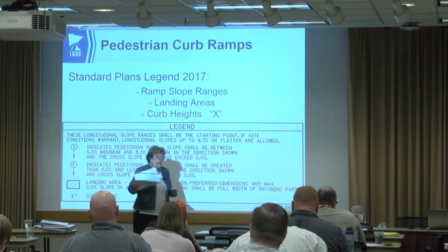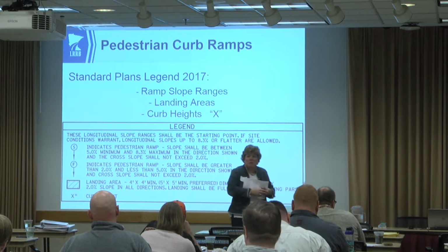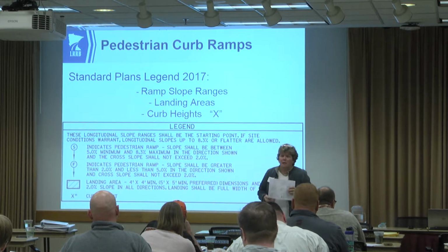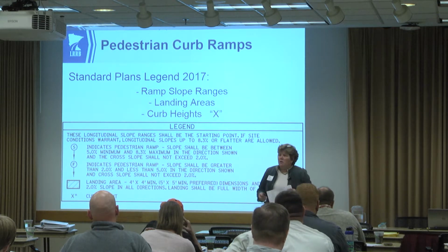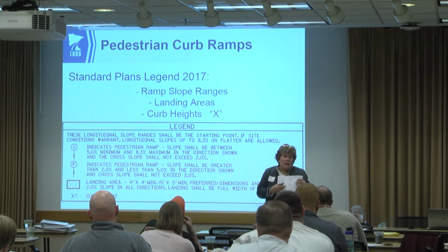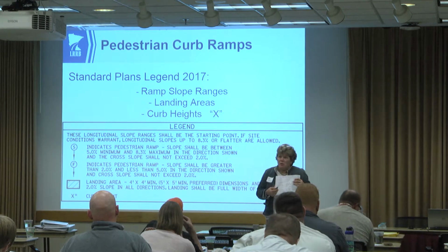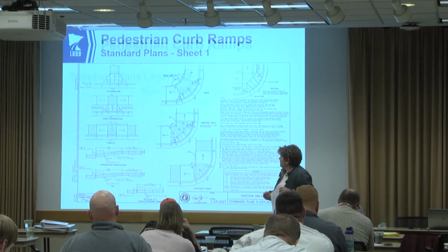Okay? So keep in mind that there's different situations. You may or may not have a steep slope. It's not like you have to build a steep slope, but if you have a steep slope, you have to allow for a landing. Also remember that a landing is going to be shown on any of these details where you have a change in direction or you have more than one direction.